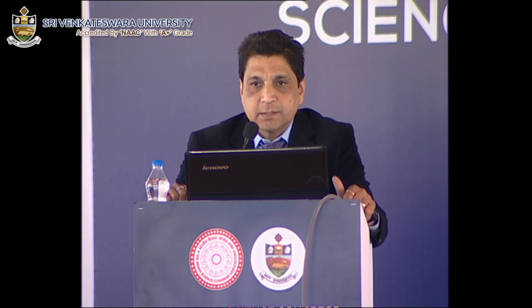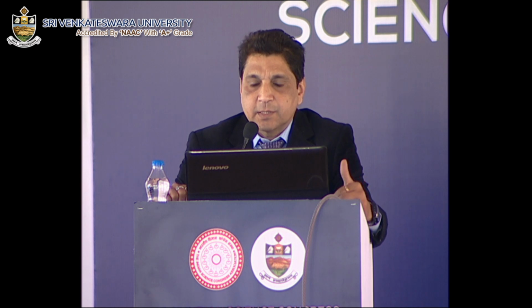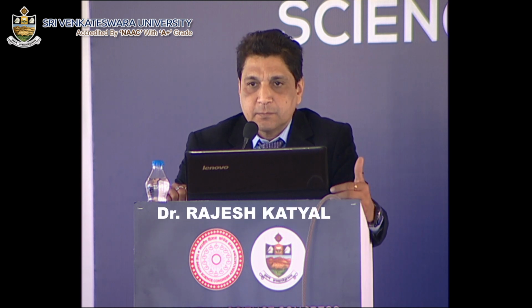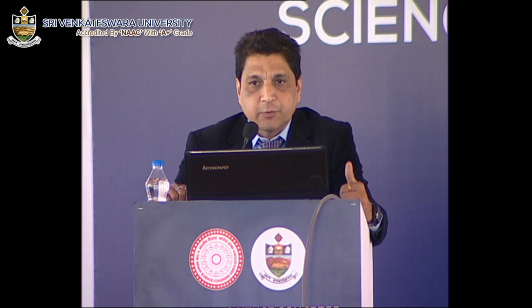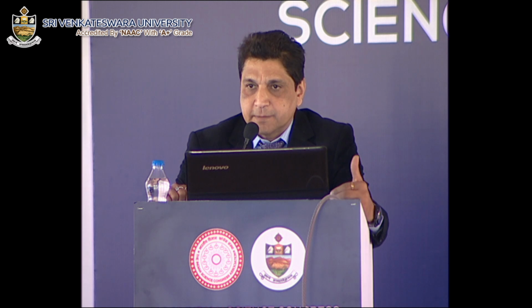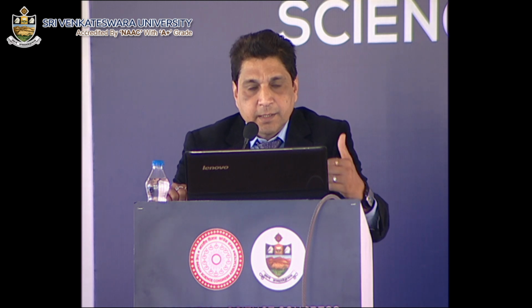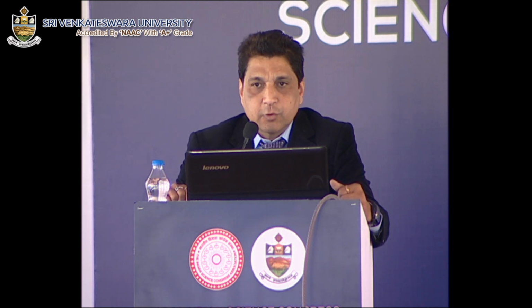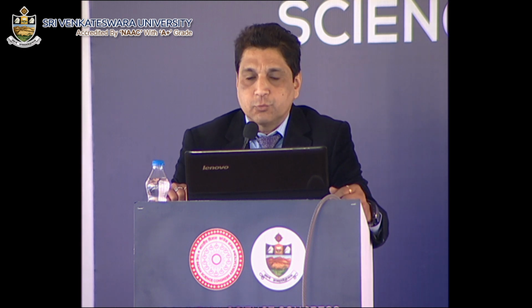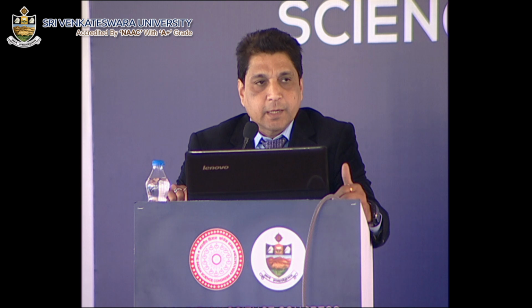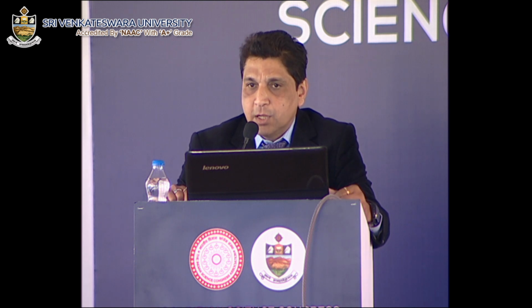And once the turbulence intensity is low, the wind speeds are always higher. Because of that, we yield about 15 to 20% extra when we put up the turbines deep into the sea. In turn, we are expecting plant load factors, or capacity utilization factors, to the tune of about 42 to 45%, compared to about 24 to 26% normally available on land-based